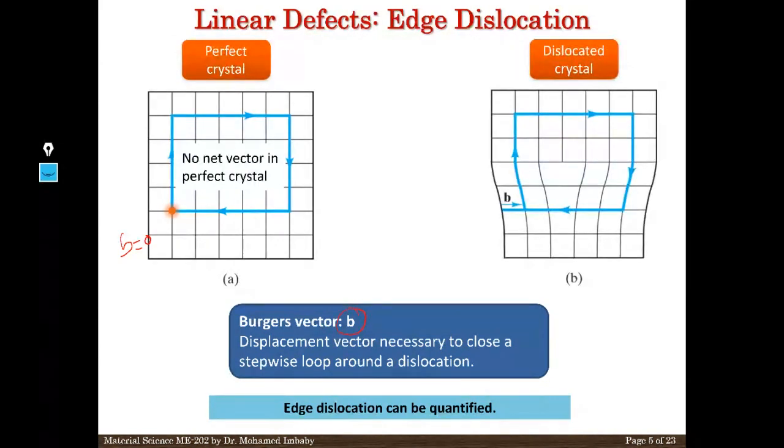But if you go here, the missing line of atoms or dislocation is there. You count it in this direction, you will find it. Like I give it to you. You count it. This is 5, for example, and this is 4, and this is 4. So it's missing 1 here. The one that just makes balance between them is called the Burgers vector, and we have here an inverted T. Is that clear? I think it's clear. This is called edge dislocation.